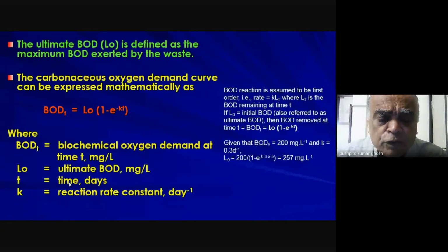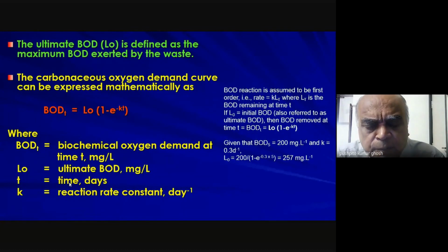Now, what you also need to remember is that the BOD is typically, as I told you, measured after 5 days. BOD 5 is what most people will refer to. But it doesn't mean that after 5 days you have necessarily chewed up all of the biodegradable substances in your effluent. You have only chewed up to the extent that was possible within those 5 days.